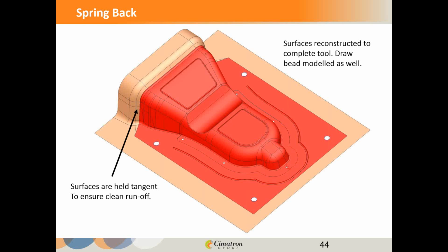If I were concerned about this and wanted to see how the 3D model draw bead actually looks, I'd go ahead and run it through the analysis again. The metal's going to act like the metal, and it's going to be constricted by the draw bead, just like you would expect. So we go ahead and run it, and not use that predictive draw bead like we did before.